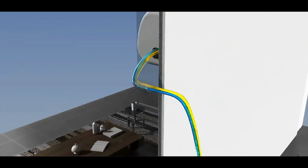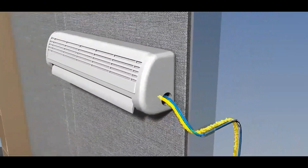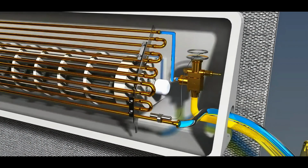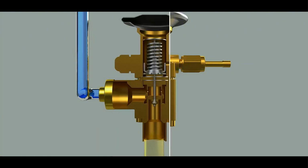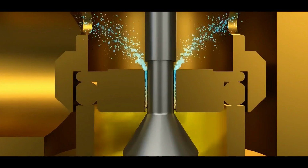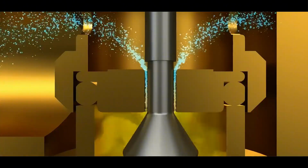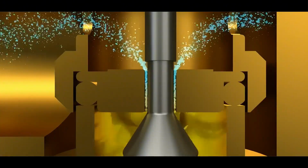Although the refrigerant has thrown off some of the heat as it passes through a condenser, it is still hot with temperature at about 50 Celsius. The refrigerant, in high temperature and high pressure liquid, flows into the expansion valve. The refrigerant, which used to flow in large space, now passes through a narrow area and its pressure drops as it goes. When the pressure drops, temperature drops dramatically as well. The cool refrigerant is now sent to an evaporator.